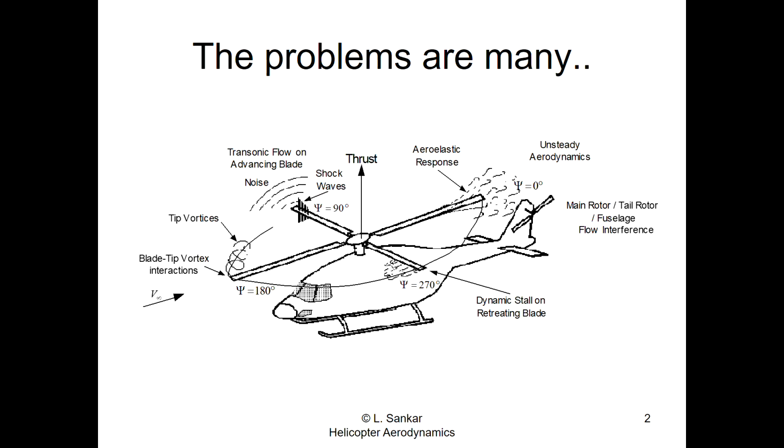Some of the other things that happen is the blades are extremely long and extremely flexible to keep the weight down. You don't make it overly rigid, so you make it pliable, flexible. So the blades bend up and down because of these cyclically varying aerodynamic loads. They also twist up and down because of the cyclically varying pitching moments. Therefore, you experience a lot of stresses all over the blade, so cyclical fatigue can occur. So aeroelastically, the blades are behaving. So these have to be considered. These need to be included in the motion of the helicopter.